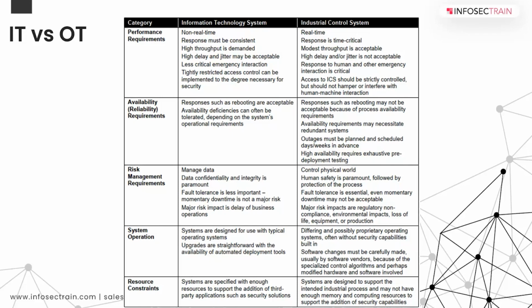Because every downtime needs to be scheduled. So you can only patch during certain periods of downtime, whenever the bigger or heavier equipment needs to be maintained, and this happens yearly or annually or once in 3 years, depending upon the type of equipment that we are talking about. Different types of industry have their own downtime schedules as well. It's called a turnaround and so on.